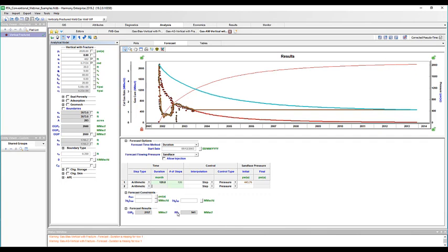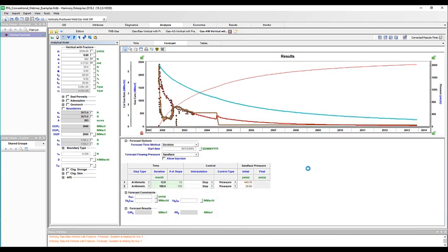Now, we know the back pressure impacts the rate, and that's true. So the well's assuming a flowing pressure of around 443 psi into the future. Now, what if we wanted to schedule a compressor or something to reduce that pressure to something a lot lower, to, for example, 50 psi? We can see that when I drop the pressure after a year, I will get a slight rate increase, as we can see here. So what we can actually do is sensitivities on different back pressures and see how the rate will actually benefit the response.